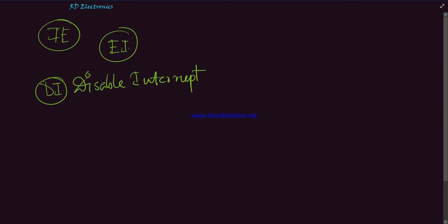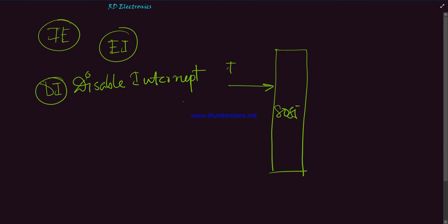This is a 1 byte instruction, and it should be included in a program segment where an interrupt from an outside source cannot be tolerated. In an 8085, there are 2 pins associated with it. One is INTR, which is called interrupt request, and another is called interrupt acknowledgement.